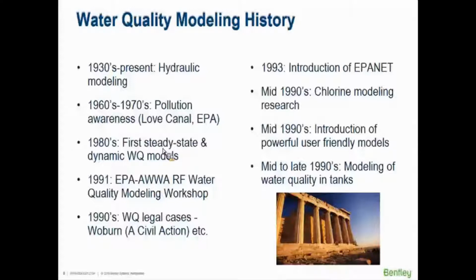And as we're going to touch on in the workshop a little bit further along, with those mixing devices that are put on tanks, while they were sold very frequently, sometimes what you'll end up with is a tank that's locked out hydraulically from the system, that the mixer hasn't really helped alleviate that issue, but what it's done is provided you really well mixed old water. So we'll touch on that too, about tank mixing and water quality modeling.